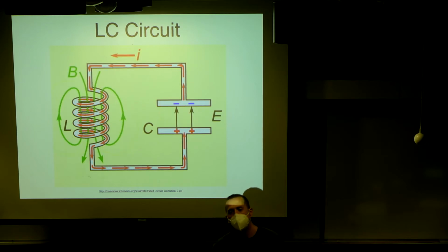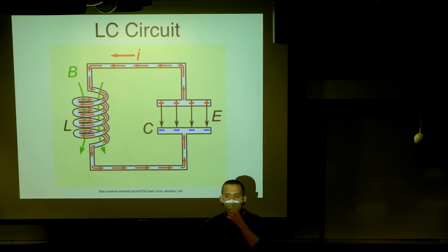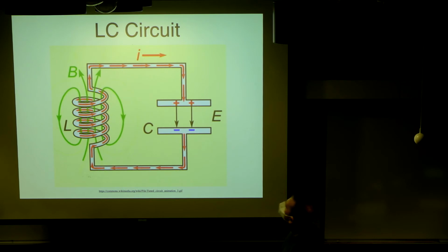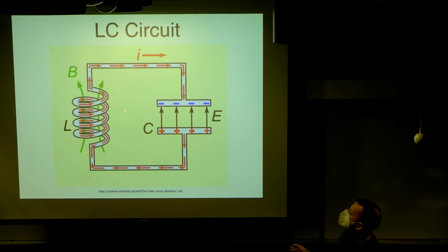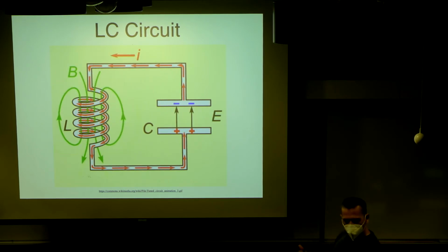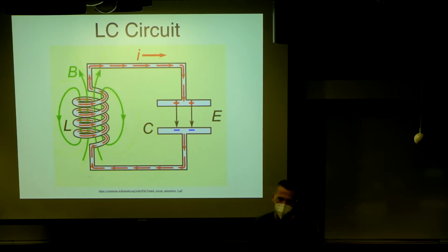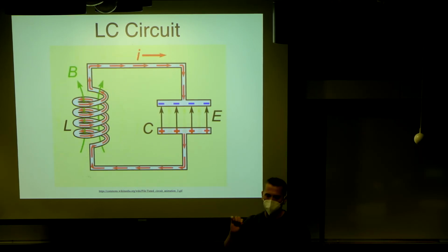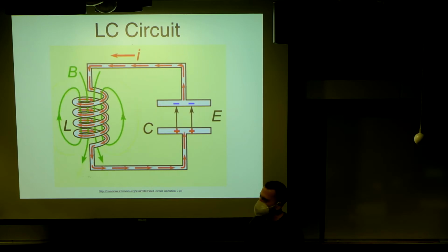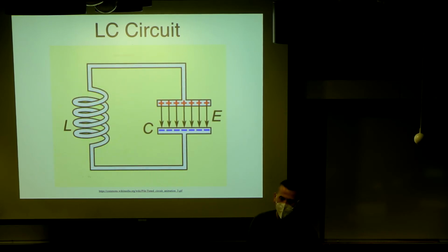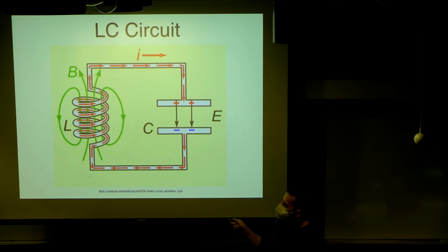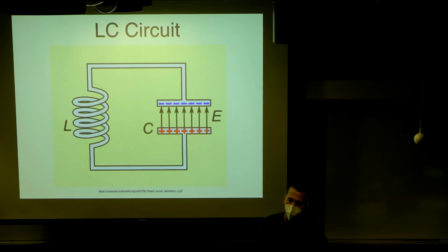Why does the direction of the current switch? It just comes out of the math, but an important thing to make that work is that the voltage across an inductor has a little negative sign. It opposes changes in current, and it would not work out to the solution we got without that negative sign.